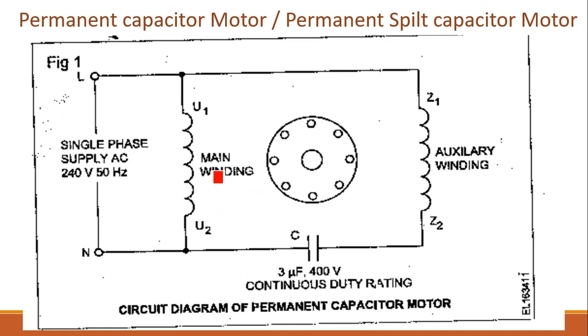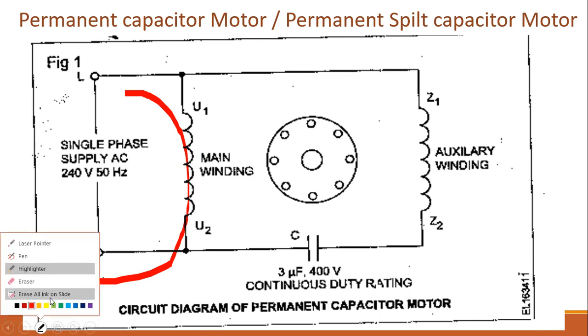And the direction of rotation change in a washing machine, we already mentioned, is very easy. Let us see the conditions in this picture. Let us say it is rotating in one direction with these connections. The main winding is taking a current like this, and the auxiliary winding will also be taking a current.